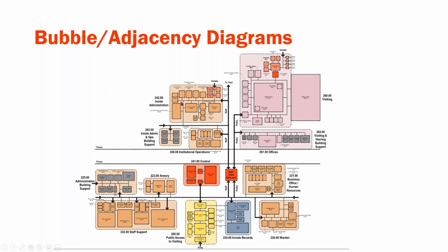Basically, we'll do some diagrams like this, or we'll use some families overlapping, and I'm hoping to script something for the rooms that are touching, or what the adjacency should be, because the adjacency rules inside of the space programming tool will run the existing tool that's in Revit now to check all of those, whether it's from this door to this door, or center of room to center of room, or adjacent. It'll go through and check those. So to me, that's next on my list of what I want to work through to see how we can use that.